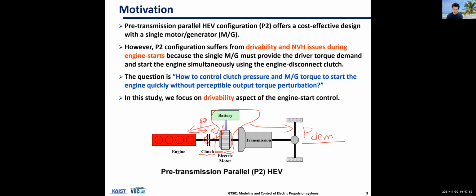But if you slowly start the engine using a low pressure clutch, then what's going to happen? Well, then you may not experience a lot of torque hole, or you can probably get close to the power demand, but because engine start is delayed, passengers will not be comfortable with that, right?